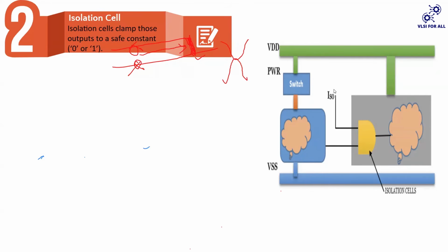Okay. And this has to be placed. See, the isolation cell has to be placed in the domain which is turned on. I have not placed it somewhere here. Okay. If you look at the placement of the cell, I'll explain in the forward lectures. If you look at the UPF, the placement of the cells are also strategies which have to be decided, right? For example, if this cell is itself in the power-off domain, then how will this cell work, right? If Abhi also gets drinks up and he also loses his control, then there is no use, right? He has to never drink it, right? So that's why this has to be placed in the always on domain, not in somebody who can be gated. Understood? Yes, ma'am.